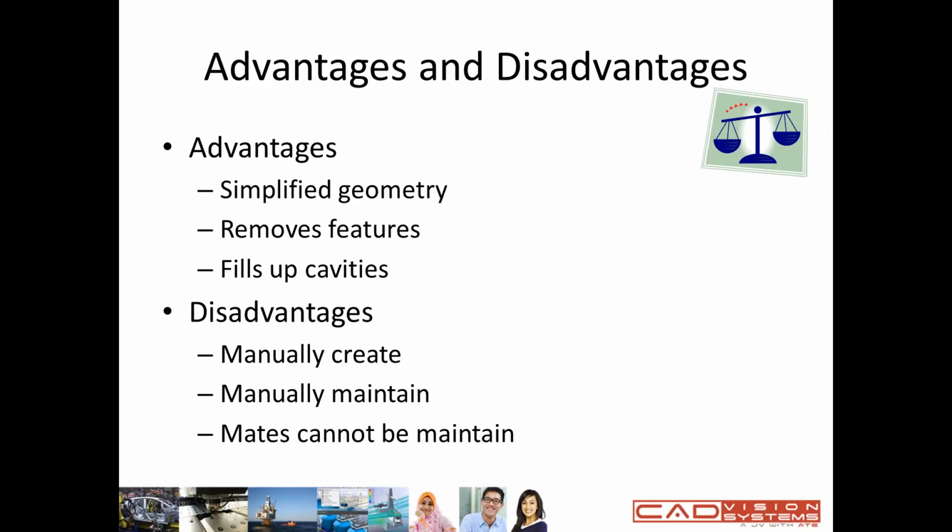So when should you use defeature? You use it when you want to simplify a part or assembly, when you want to remove some parts, features, or cavities. Another case is when features should not be exposed, so there is no feature history or no dimension or tolerance. So defeature is a good thing to use.